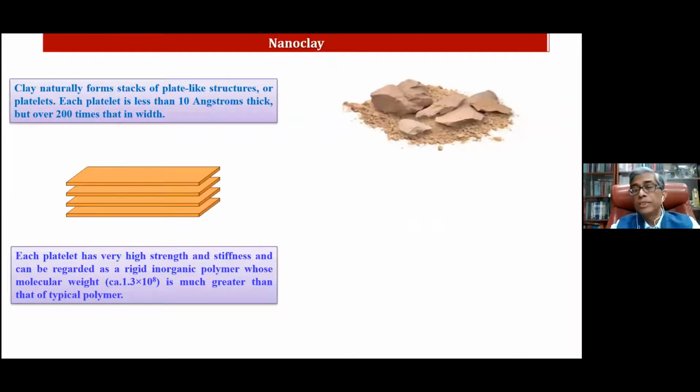I showed you these nanoclay structures in my earlier slide. These are montmorillonite nanoclay, which are now becoming readily available at quite a comparable price to some of the particulate fillers we are using nowadays. And remember, once we use this, we have to use much less than the microfiller, so there is a win-win situation with nanoclay. If we look at it, it just looks like a powder. It's like a clay, like a mitti.